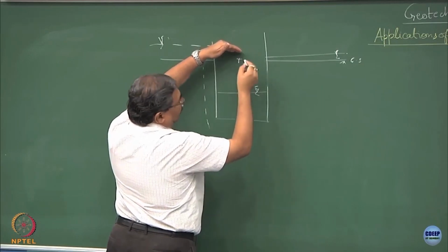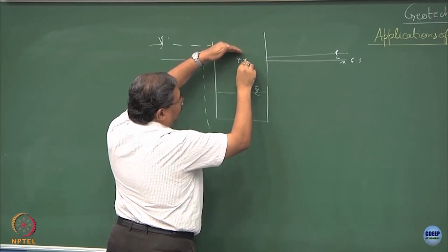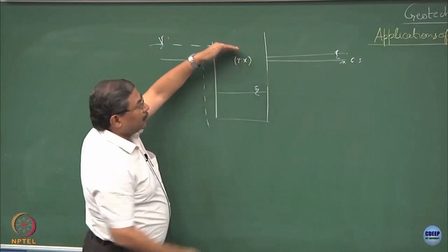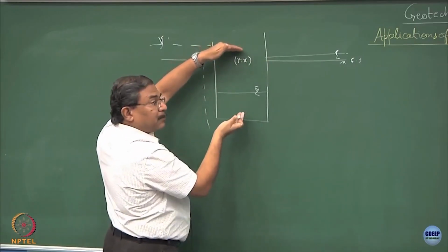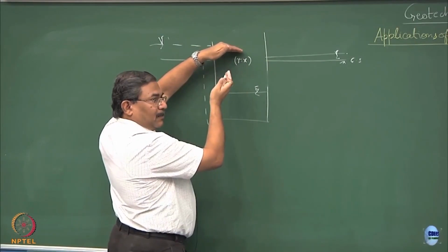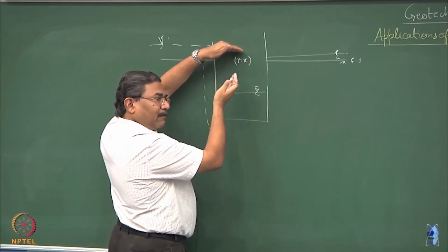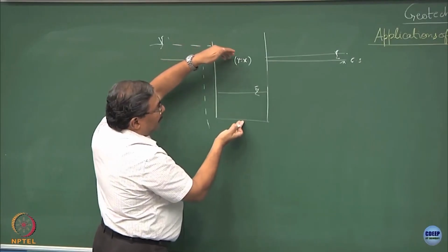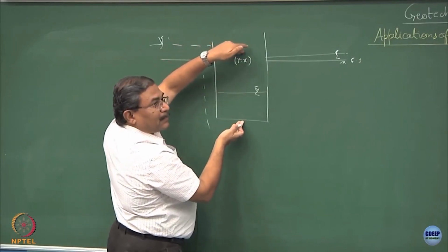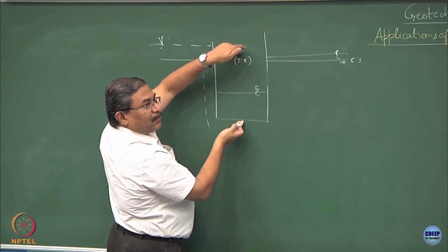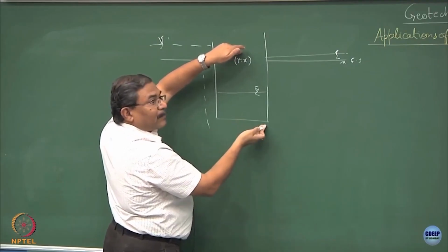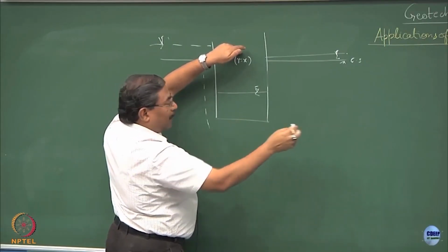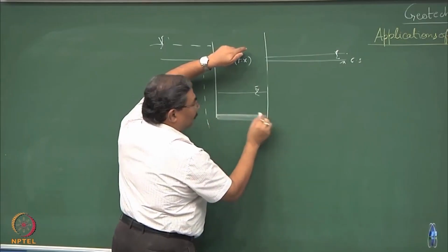Gamma of the soil multiplied by excavation x. This much stress has been distressed. You understand the word distressed? By excavation, this much block has been removed. So, at this point, gamma into x is the distress which has been applied. I have been telling you repeatedly, if I do not put a raft over here, what is going to happen?